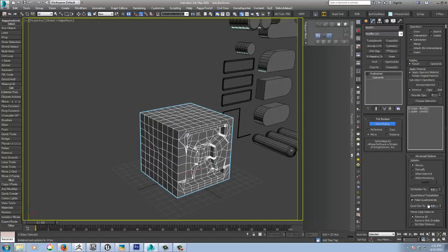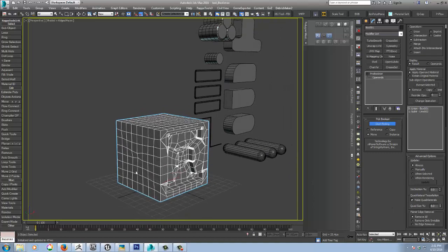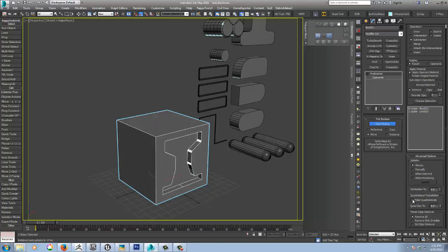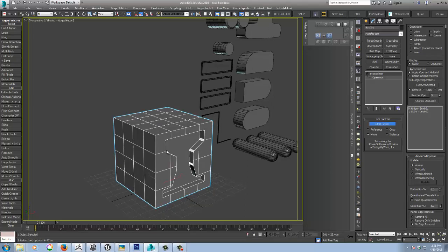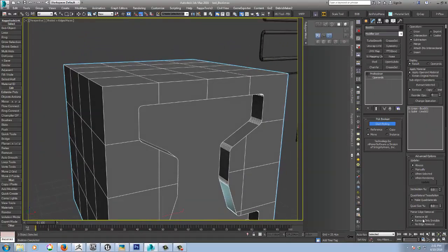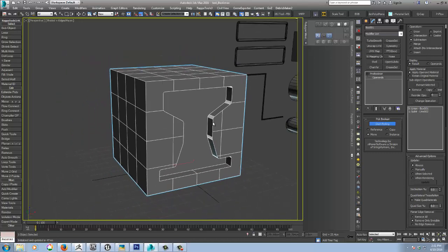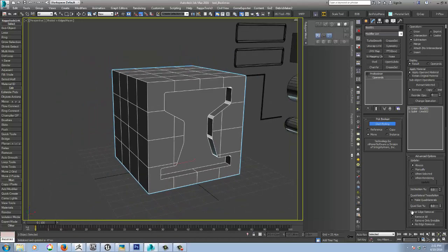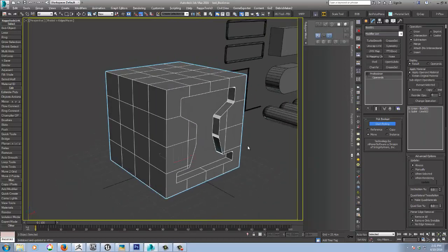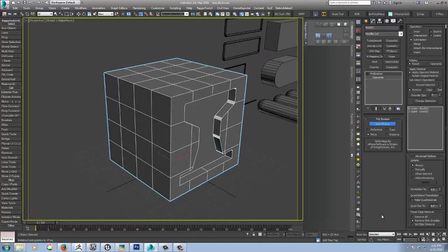the percentage. The lower it is, the smaller the quads, the more quads you're going to have, and the more the Boolean operation has to work with. So I'm going to actually leave this off for the moment. And also this planar edge removal, usually either have it to remove all or no edge removal I would not use. You'll see when we add the chamfer modifier, so it's either this remove only invisible or remove all. So I'm going to leave it on remove only invisible for the moment.